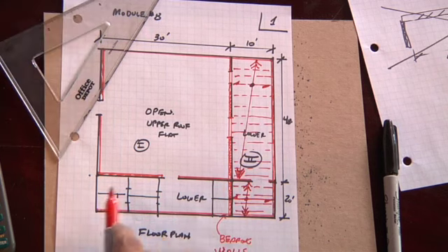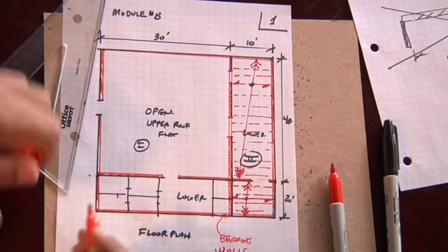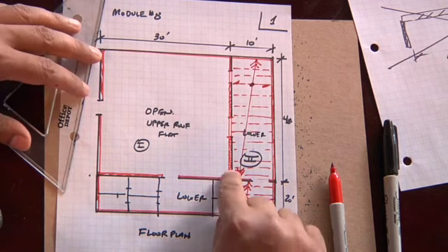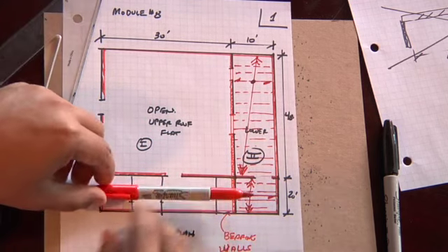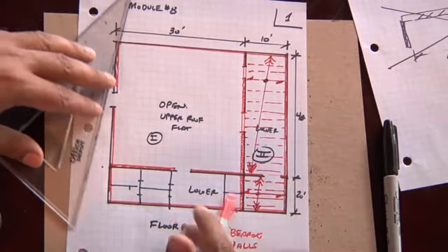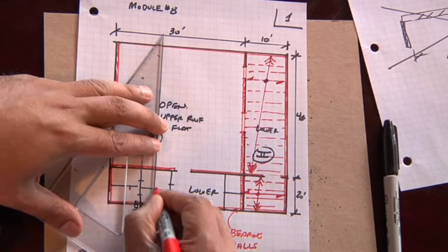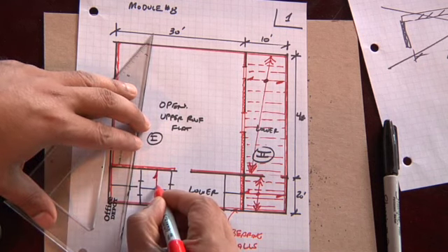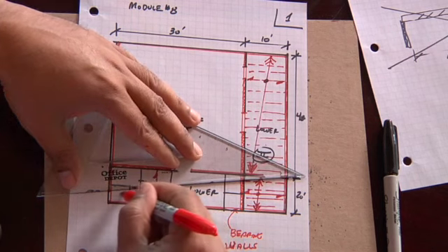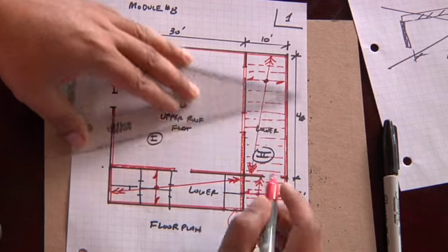In this direction, and I forgot to label this as a bearing wall, so let me do that really quick. Here again, we have the same situation, except that now we have a 20-foot short span versus a 30-foot long span. So naturally, we don't want to space our joists along the long span. So what we're going to do is shift the joist spacing, and we're going to run, again, across the short direction. And I'll use my notation here. That's the direction of the joists, and they're going to go from this bearing wall all the way to that bearing wall.